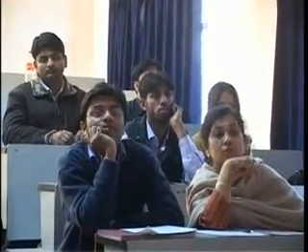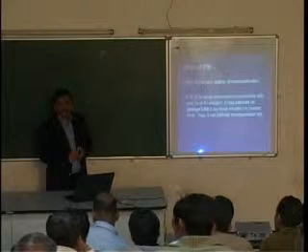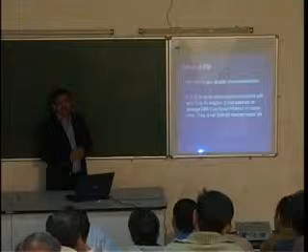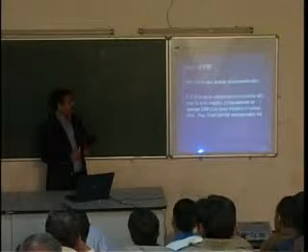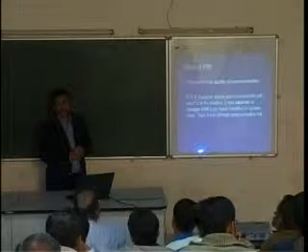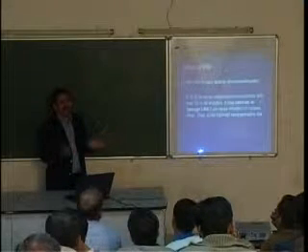It is a very common problem. In the 1980s and 90s, people started worrying about this, and now international standards ask us to measure whether passive intermodulation product is getting generated or not, because in any feed in any antenna system we never use one single material.